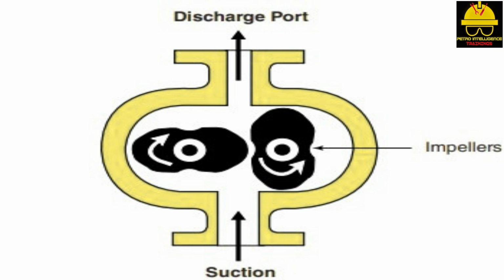Lobe compressors are designed to have constant volume discharge pressures and constant speed drivers. Lobe compressors do not use discharge or suction valves because they are not designed to operate at a specific pressure. Discharge pressures are determined by the system's process pressure. Lobe compressors can be used in wet and dry gas service.